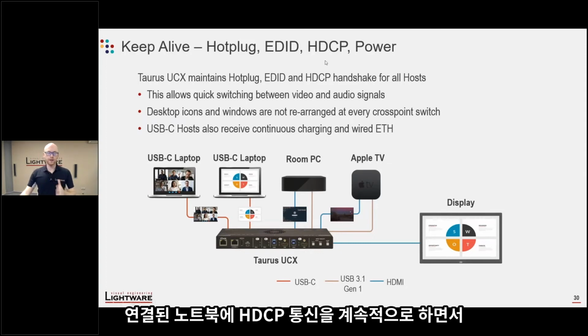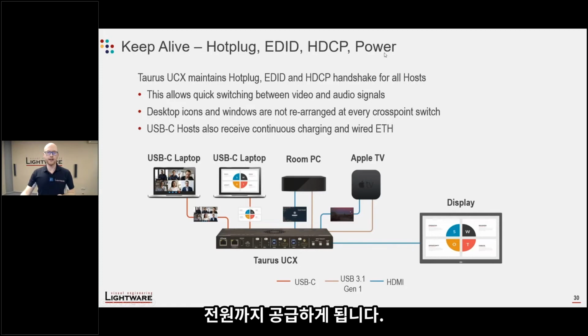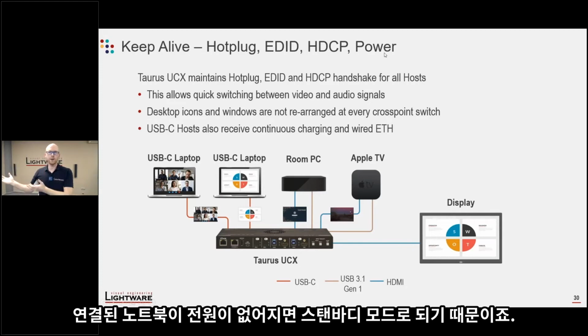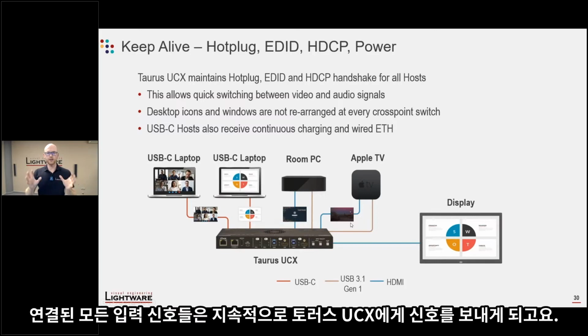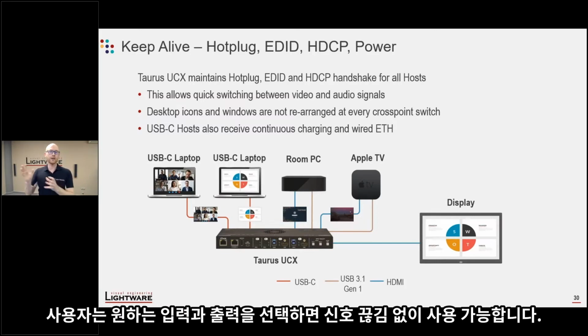We provide a continuous HDCP handshake, and to the USB-C laptops, we also provide power, because with laptops, the laptop might turn its display off or go into standby mode if it's not receiving power. So there are different policies for battery operation and connected-to-an-outlet operation. So all of these sources are continuously sending their signals into Taurus UCX, and you can decide which one to send to the display or which ones to send to the displays.